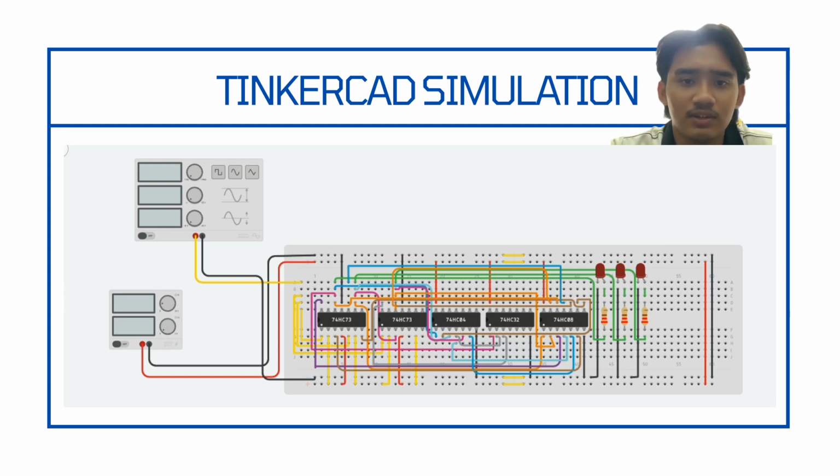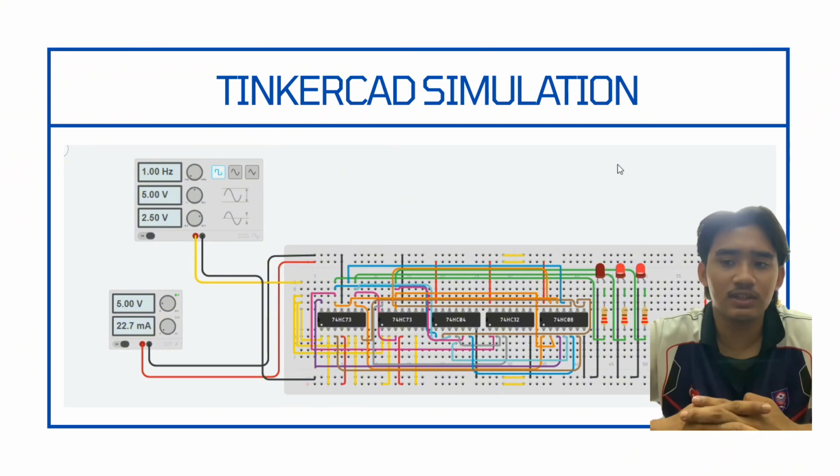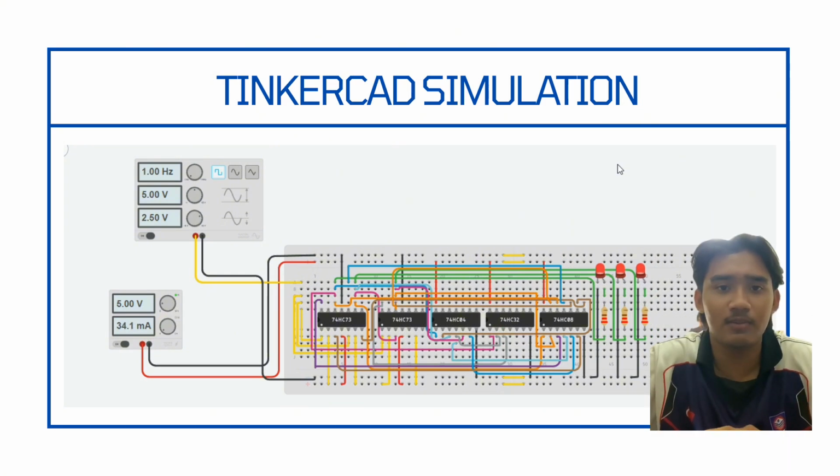The system is driven by a shared function generator, providing a square wave clock signal synchronously to all flip-flops, while the clear pins are tied to VCC to bypass the reset during operation. The behavior of the FSM is determined by state excitation equations derived from the state transition diagram. I have carefully wired the combinational feedback path as follows.